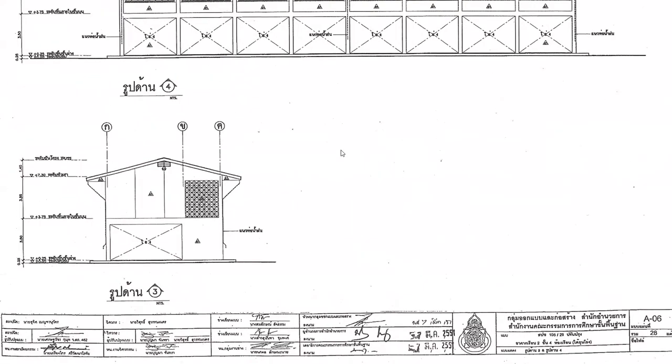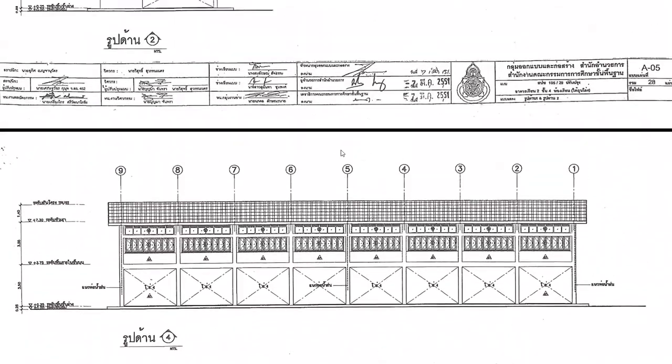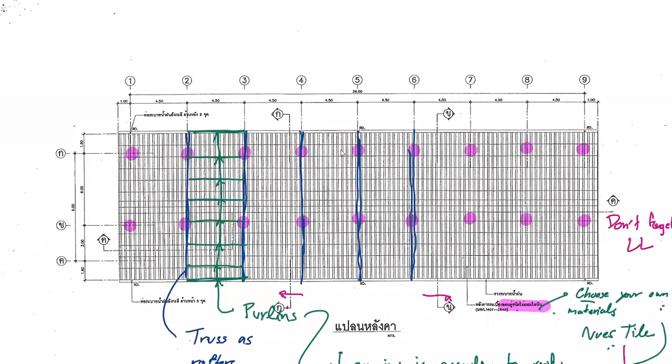Okay, anyway, this means that when you face a problem like this, you don't hide by saying, hey, architects, don't show me this. The 2 cross sections, they look this way, so you see this instead, and then this one looks this way, so you see this part instead. It doesn't show the most important information that you need. That is, at the corridor you don't have columns. When you face a problem like this, you must try to verify this from the beginning with architects.